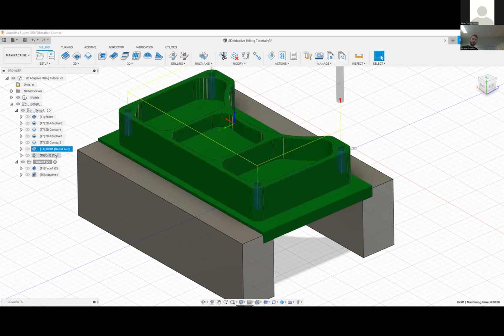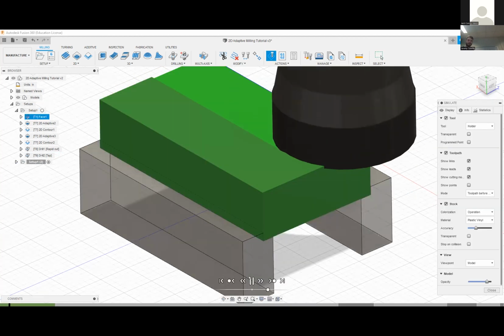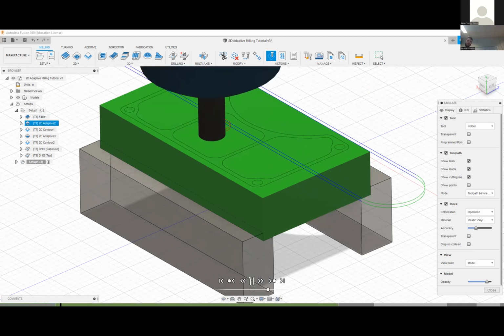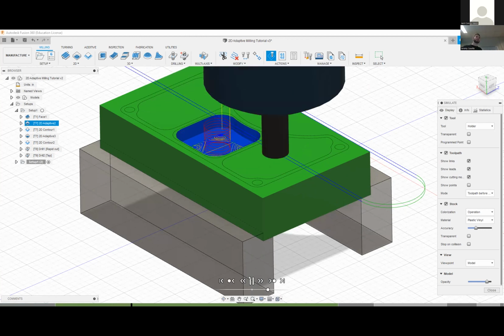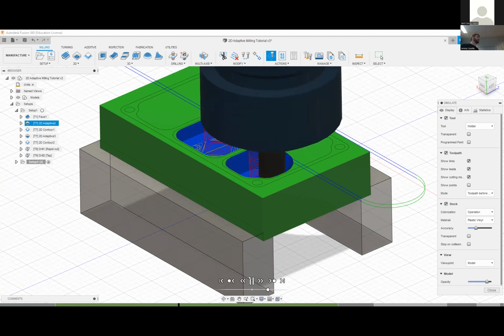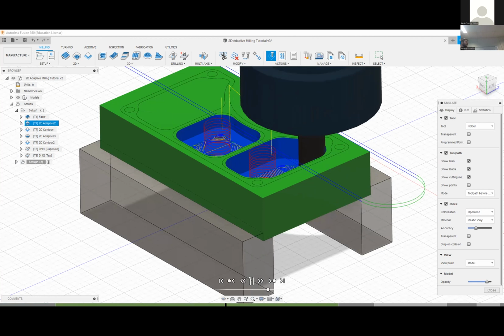And so if we look at this toolpath here and we ignore this second one that I was messing with, we simulate that, we'll see that we have everything we need to make a part, right? As a design engineer, you won't put these really tiny radii in the corners because you'll know that it'll make me sad. And you don't want to make me sad. It will also drive up your part cost, increase your scrap rate. Lots of other things can happen when you make really complex features, right? So keep it simple. Do what you need to do to make the part functional.